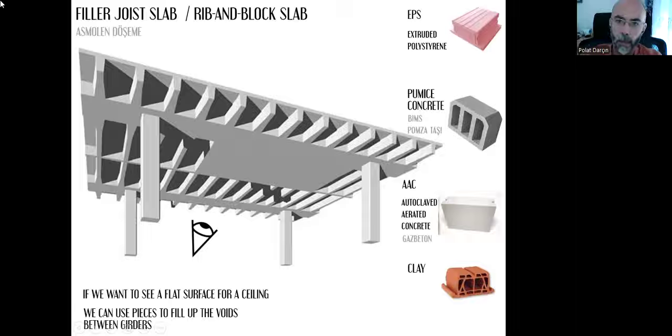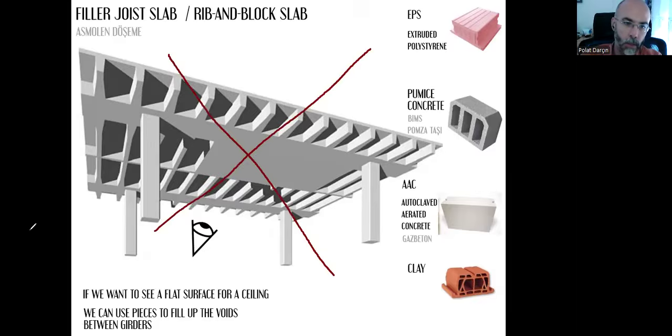But please do not forget, again, where there is risk of earthquake, we shouldn't prefer that type of flooring because it is heavy. It's heavy and we don't want a heavy load over our columns and beams. So, and it's thick and it's not flexible enough. So, we shouldn't prefer that when there is a risk of earthquake.